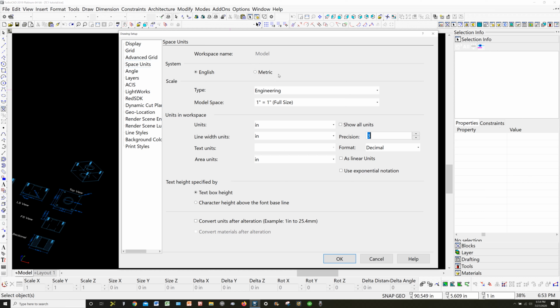This is very important because if my end user is always looking at metric, when he imports my CAD drawing, you want to give him his primary unit measurement. CAD doesn't care whether you are in English units or metric units, whether you're looking at inches, feet, yards, miles. A unit to CAD is a unit. So it's very critical you tell it what unit.